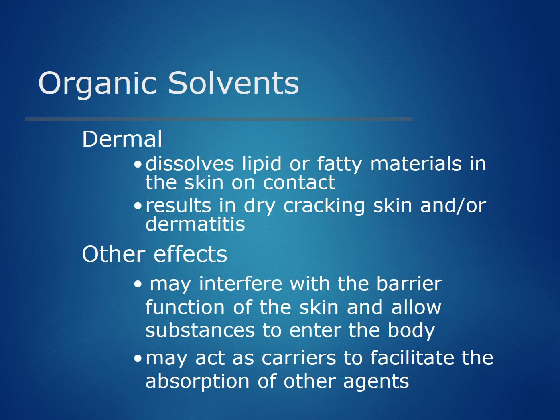From a dermal standpoint, organic solvents dissolve lipid or fatty tissue when they come in direct skin contact. This can result in dry, cracking skin and/or other dermatitis, reddening of the skin, or rashes. Other effects may include interference with the barrier function of the skin and allow other substances to enter the body.